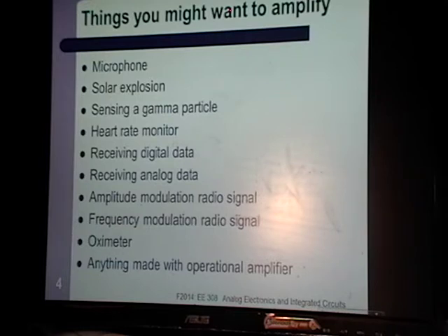The signal is probably on the order of, hopefully a little bit bigger than, the noise in your circuit. So a low noise amplifier is a technique of designing amplifiers so that the internal noise of the circuit is as low as possible, so you can receive as small a signal as possible off an antenna. And that's great, 2 or 3 gain, and now you can use a regular amplifier to amplify the signal the rest of the way.